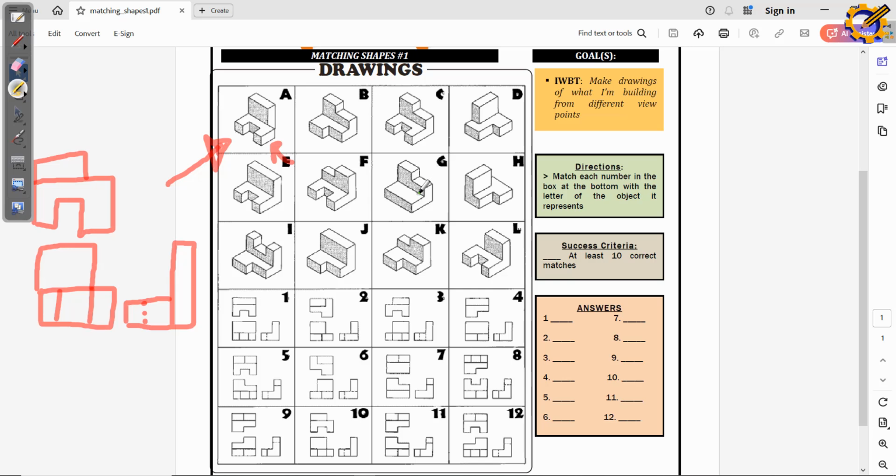From our first video, I said if you have to produce this object in Autodesk Inventor, you need to produce it from any of the views, either from the plan, this is the plan right here, or the front, or the end view. You can produce your object from any of the views. Just that if you are producing from one view, you know that you are going to extrude it to the other side of the view.